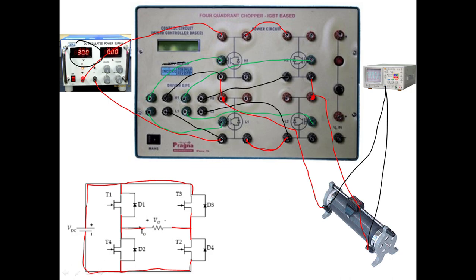Now this is the mode for changing various pulses, right? Increment, decrement, mode, everything will be present here. When you keep on pressing this mode, you will get all the waveforms. The first one was single pulse width modulation, multi pulse width, trapezoidal, and staircase, right? Once you set the type of PWM to single pulse width modulation, then you can change the duty cycle or frequency as we saw